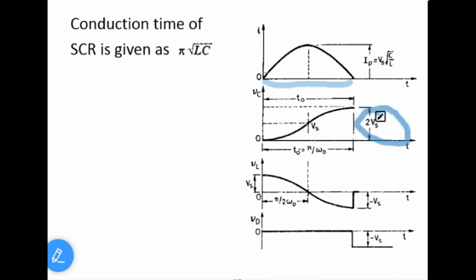Without an inductor, if it is an RC circuit, the capacitor will charge up to Vs only. Since it is an LC circuit, the inductor is delivering the energy after half of the conduction, and the capacitor voltage will charge up to 2 Vs. As I told earlier, when current is rising, voltage is positive. When current is maximum, voltage is 0, and here it becomes negative. Since the voltage is becoming negative, Vc is becoming 2 Vs.